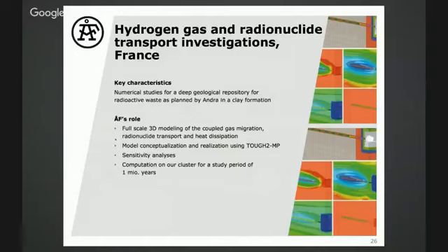We have programmed that simulation using a code called TOUGH2, and particularly for the full-scale simulations, we are forced to use the parallel version. So we actually have a fully parallelized model to simulate a repository system at the scale of a couple of cubic kilometers. We use that model on the one hand for phenomenological studies, but also for sensitivity analysis, and this on a time scale of really up to 1 million years, which is usually what the authorities ask for.